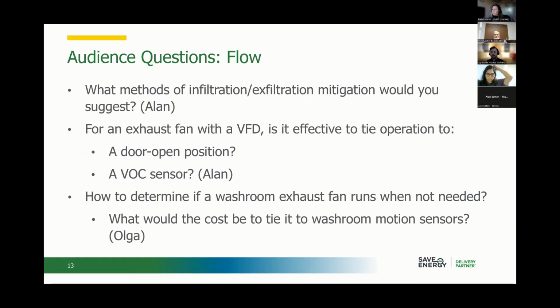So Vern, my concern on the door issue is not so much with the exhaust fan, but with the typical oversight of not looking at what other systems would be impacted by that. If you've got a building, make it a square box, the exhaust fan's taking air out of the building. If the door is closed and the fan is now on, where's that coming from? It's got to be coming from either infiltration or from another HVAC. What I'm finding is some of our engineers are really good at turning fans off or turning fans down, but not really good at figuring out what else in the system needs to be balanced. Well, that's a good point.